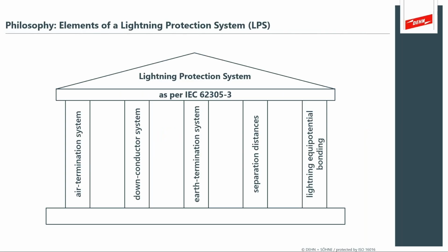So the pillars of lightning help us understand how to deal with that electrical charge that wants to move through your structure. An unprotected structure is prone to fire. So the application of a lightning protection system gives you the benefits of fire protection through an air termination system, a down conductor to get it from the air terminal down to the earth into an earth termination electrode: the grounding rods, a grid, a ring around the structure, or in many cases the concrete electrode, the foundation electrode.